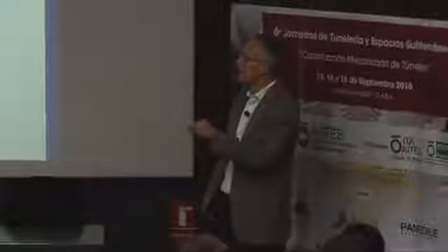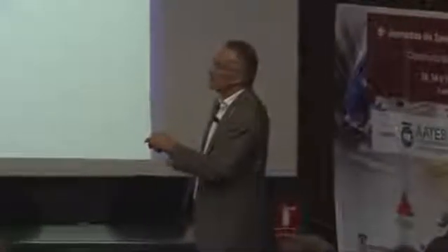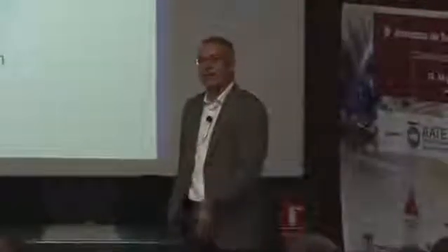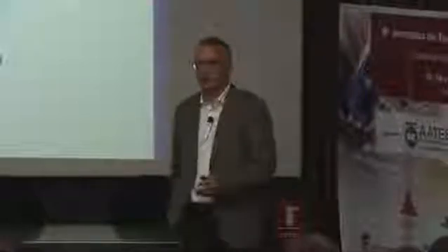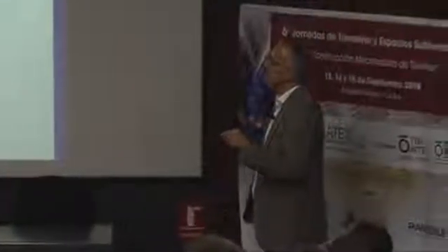When you are in the back with your tail shield, you have a very good grouting and pumping system. When it is in this position, then you can stop and make an extensive grouting procedure just to stabilize this area. That was as long as we have the TBM operational.